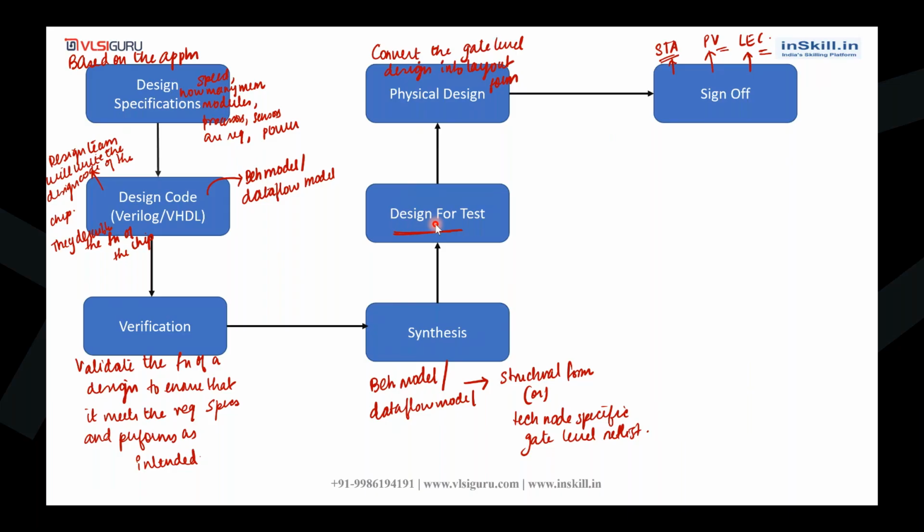Okay, so in the process of chip design, in each and every stage, our design is undergoing a lot of changes. That is why LEC is done to check whether the final design is logically equivalent to the original design or not. LEC will be done after each stage, like after synthesis, after DFT, after PD. Okay.